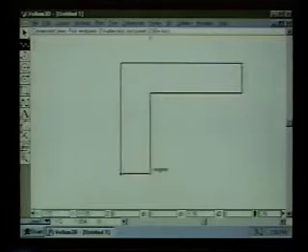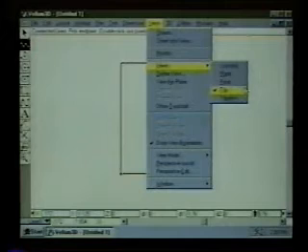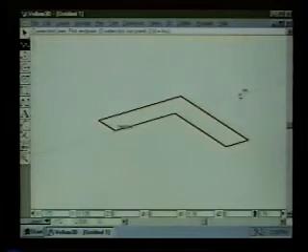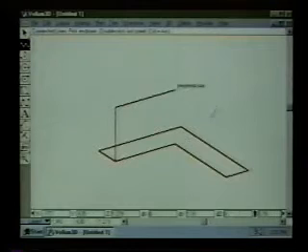Now we can actually jump right into a 3D viewing situation, so that instead of looking at the top view as we are currently, I could look at an isometric view or a trimetric view, which will then look more like this. And then from here, notice that as I get above some of these points, like for example here in the corner, it says align Z. So now I'm actually moving up in the vertical direction away from the plane that this object is lying in. So now what I have in essence is the ability to go on and sketch and find alignments for this part in 3D space.